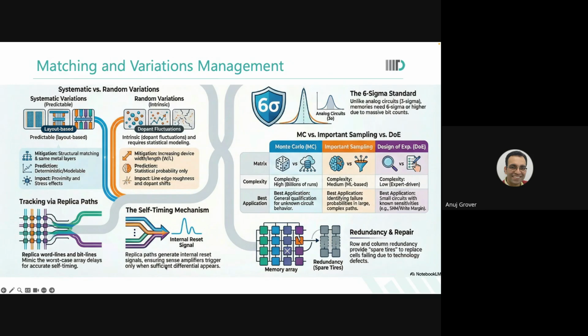And we lose on reset time, and we are losing on power also, because the word line continues to be on. Now, you have already sampled the sense amplifier, but the bitline is continuing to discharge because reset has not come. The power is also being lost. It's not just timing, it's also power.